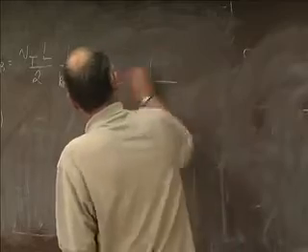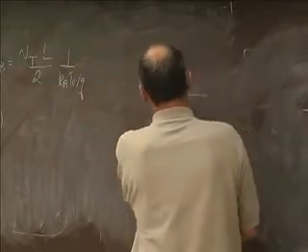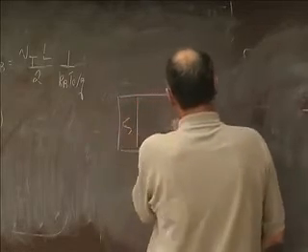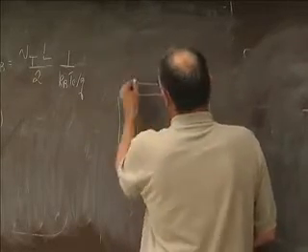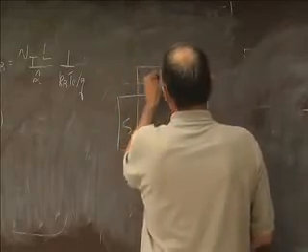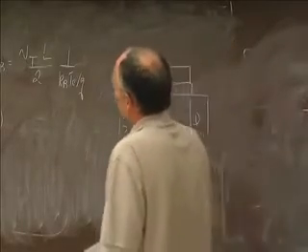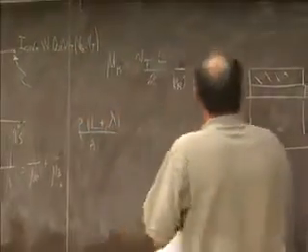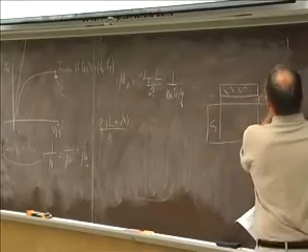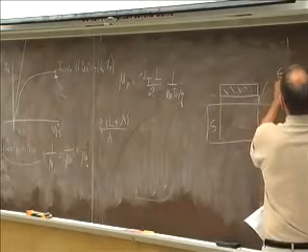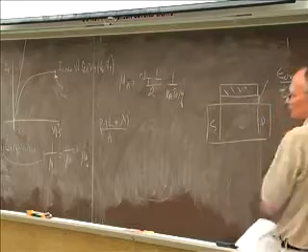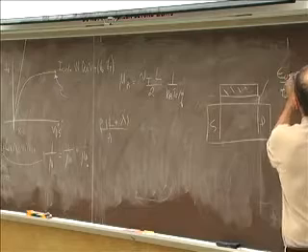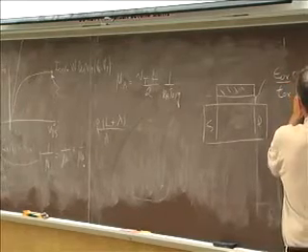In an MOS transistor, let's say I have a source, a drain, a gate insulator, and a metal. When I've been talking about the gate capacitance, I've just written the oxide or insulator capacitance. That's epsilon of the oxide divided by the thickness of the oxide, which is a little over 1 nanometer these days. So this is the capacitance in farads per square centimeter.